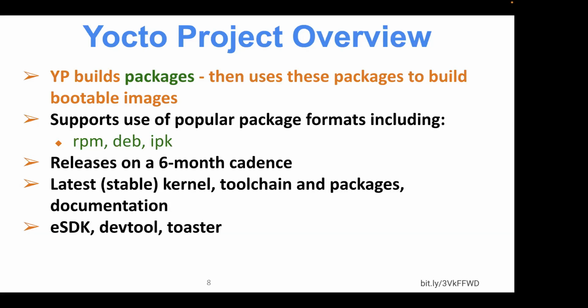And so the nice thing is on the embedded target, we can actually say what of that we want installed, instead of installing everything on the target, or some other build systems will install everything and then delete things that aren't needed and that sort of thing. Instead, with Yocto Project, and OpenEmbedded for that matter, things are built, made into packages first, and then only the packages that we need are then used to build the image that eventually goes onto the embedded target. It gives you a tremendous amount of control as to exactly what it is that's going to go where in your system.